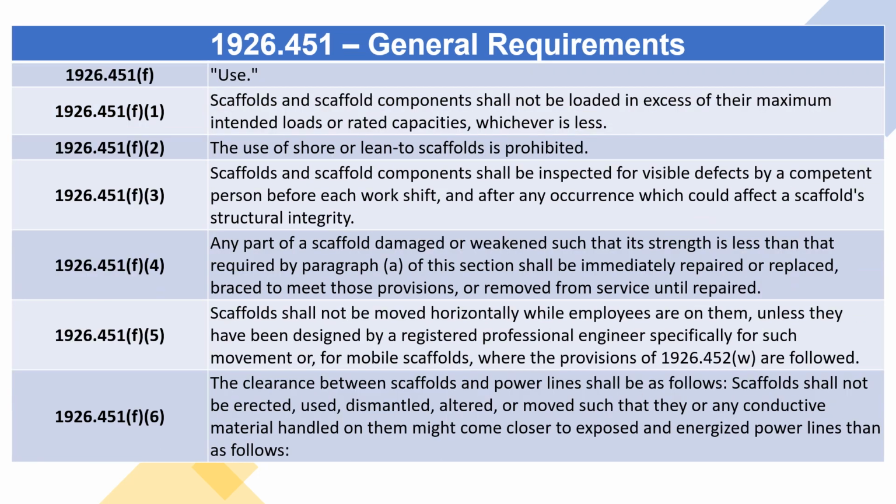1926.451(f) Use. 1926.451(f)(1) Scaffolds and scaffold components shall not be loaded in excess of their maximum intended loads or rated capacities, whichever is less.